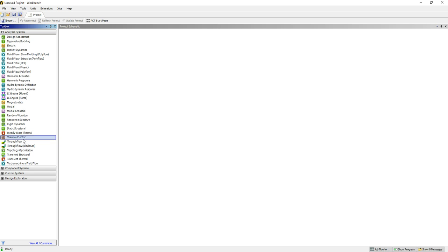What we're going to be doing as we're working through is looking at mesh, and how mesh is the overall controller of everything that you do, the visual representation of the geometry that you do. When we get to explicit dynamics, we'll go on to the latest type of technologies in the mesh, which is nicknamed the corrosive mesh. Basically, mesh can have a Young's modulus defined between two nodes, and when it's extended, if it's extended enough, imagine there is a spring in between these two nodes. If it's extended enough, the spring will snap, and what you can actually end up with is debris.